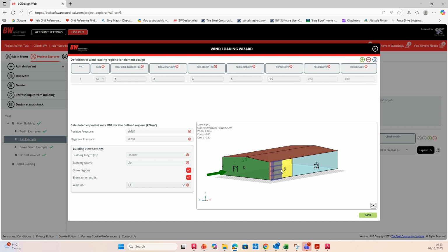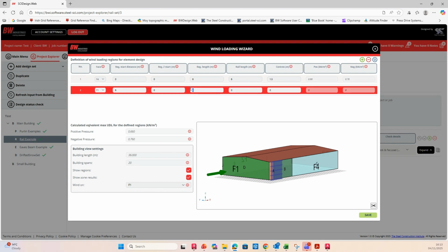We can now go straight over and have a look at the calculated pressures. Add another zone in if we wanted to do an inner bay. We then add the diameter 6 and then copy the other information down, and then calculate to add it. There you go.